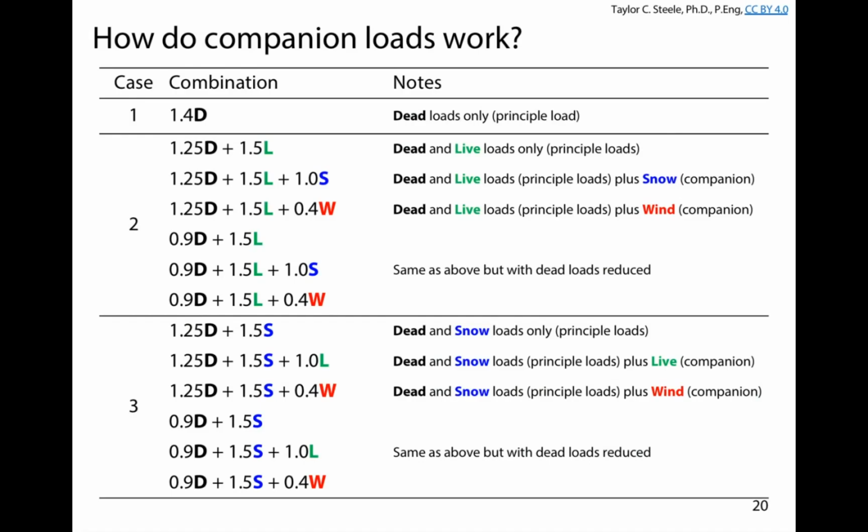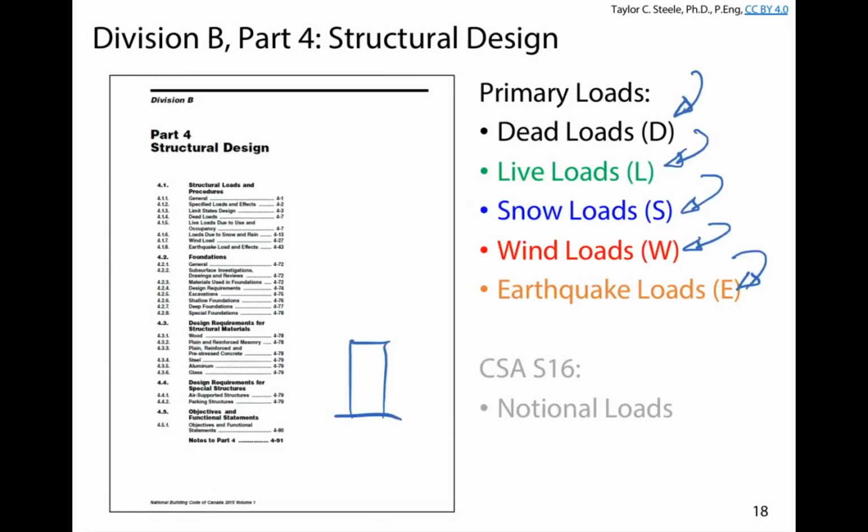A simple case might be we've got wind blowing on our structure, and we have a certain weight of the structure that's holding it down. This isn't necessarily a consideration we're going to talk about in this class, but there is a geotechnical consideration that you're thinking about currently in foundations: preventing overturning, right? We want to prevent overturning of our structure with a certain acceptable probability of that happening. If we overestimate the weight of the structure, but it's actually less, what's likely to happen to our building when wind's blowing on it?